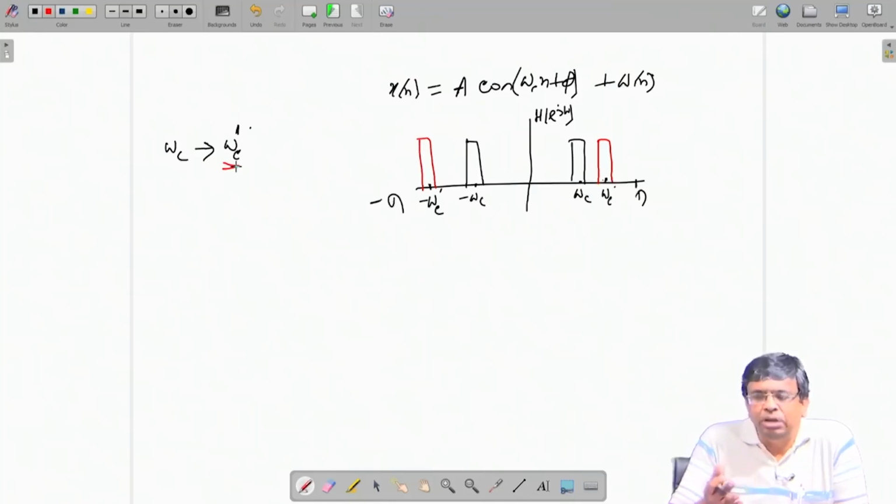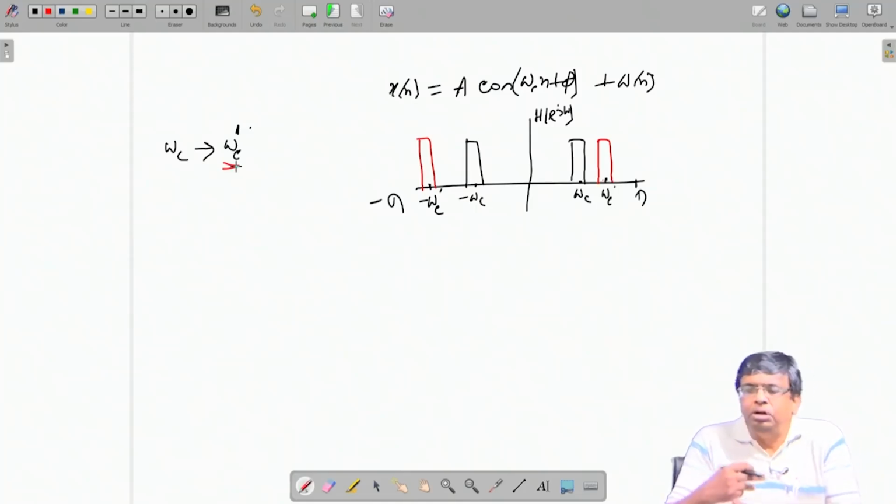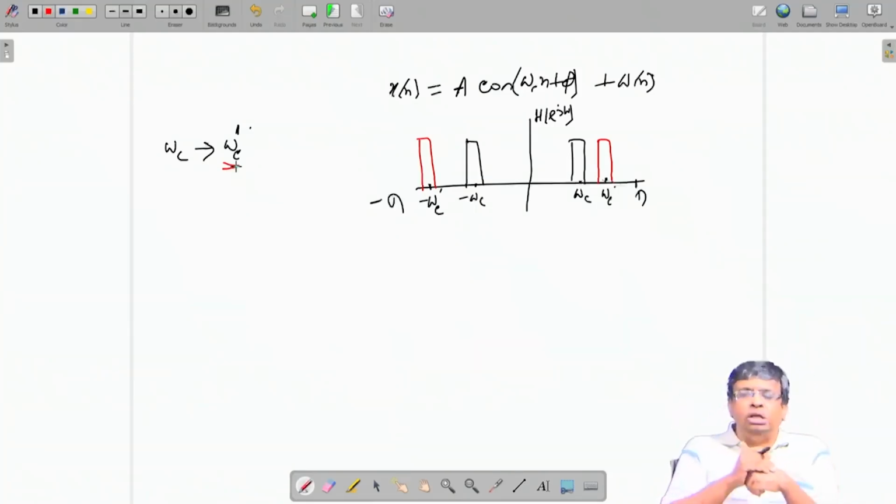This adaptation mechanism, when you impart it to a filter, together is called an adaptive filter. In an adaptive filter, coefficients are not held fixed; rather, they are flexible through an internal algorithm of adaptation or adjustment. They are continuously adjusted from clock to clock, so that depending on the circumstances or surroundings, it always goes to the best filter. This is called an adaptive filter.